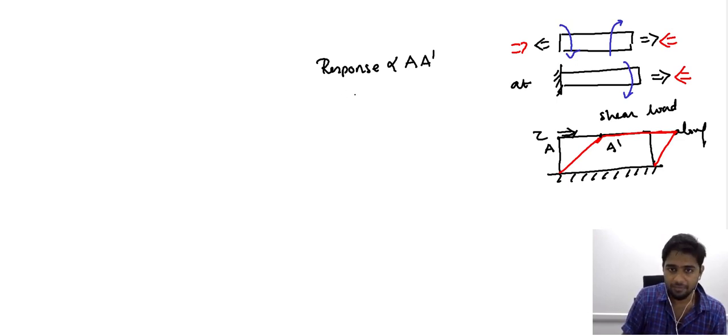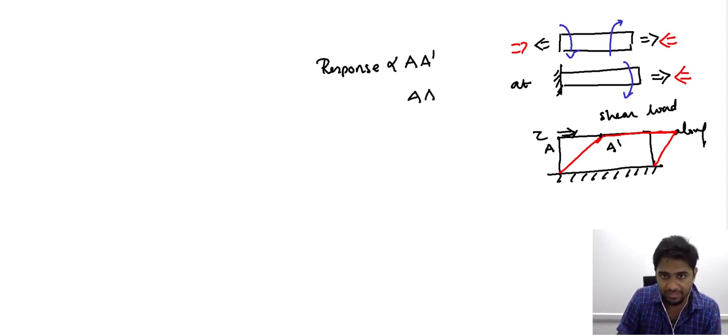Now if we want to talk about the strain, if we want to express the response independent of the dimensions of the sample, we take the ratio of the shift in the corners to the original dimension of the sample. That is, we take the side that experiences this shift. We consider the side that has moved away from this point to this point. So the length of the side is OA.